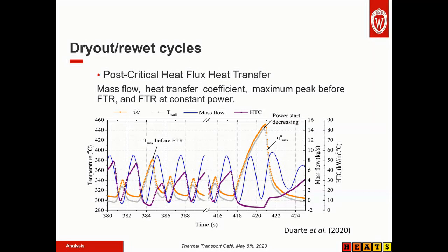So what's the flow regime there? In small channels, we typically see annular flow, but you have obviously very large channels. But in the schematic that you showed, you always showed bubbly flow towards the end. What's the flow regime there? It's annular flow to dispersed flow. It's very high void fraction. Okay, all right. But the schematic that you showed did not show that actually.